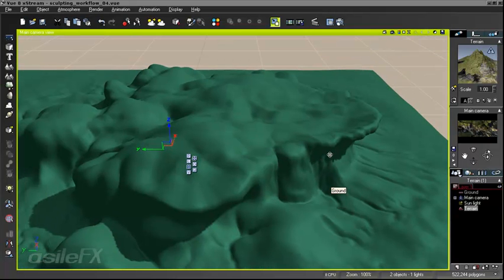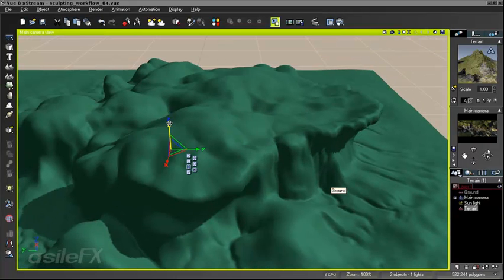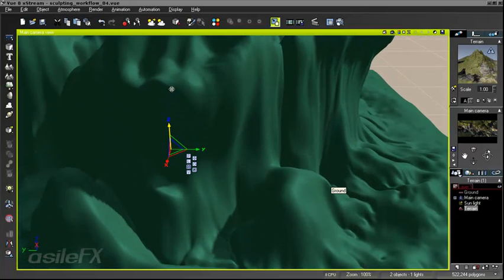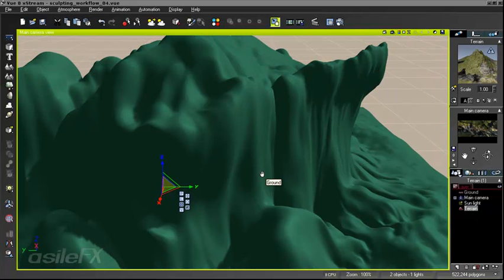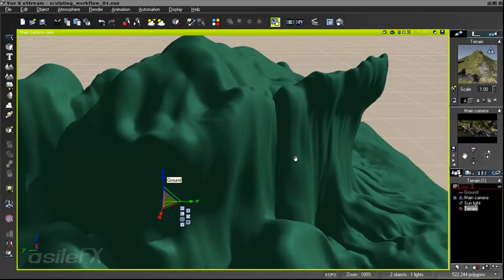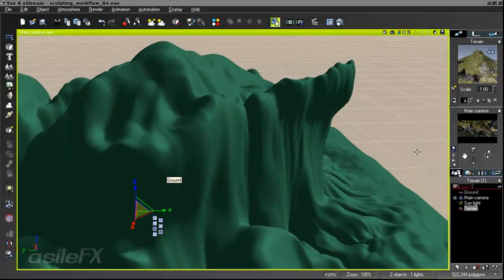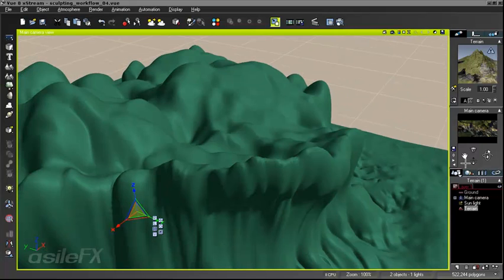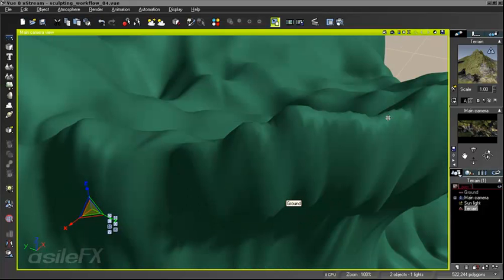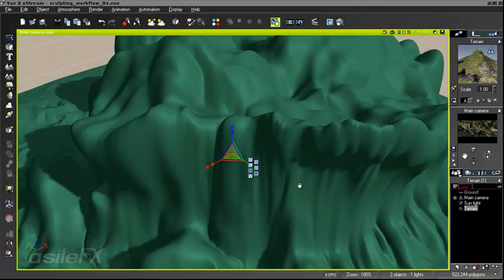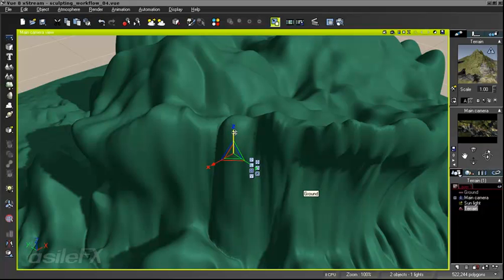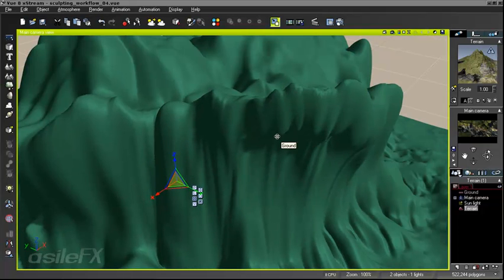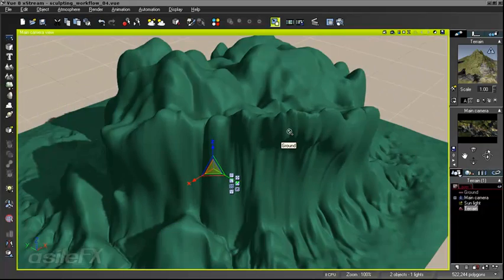Another trick to help you work on areas of a terrain is if you scale the Z higher than what you intend to have. Sometimes you can see directly within the main interface some of the issues by the different levels of geometry, and it also gives you a slightly larger work area when you're in the terrain editor.